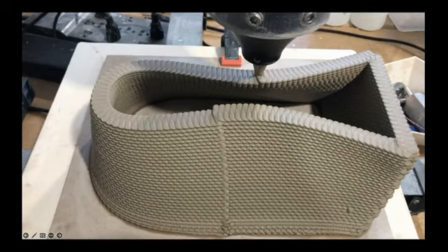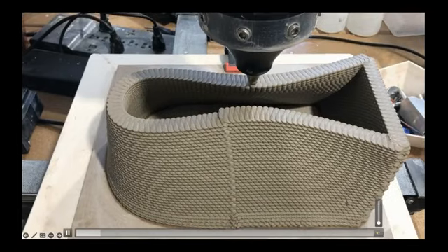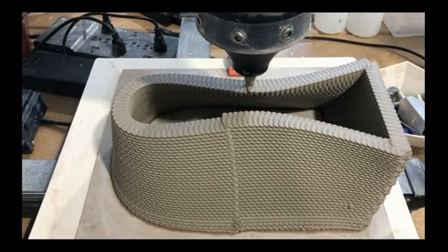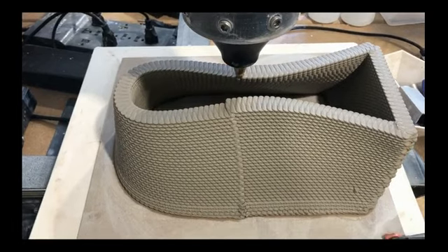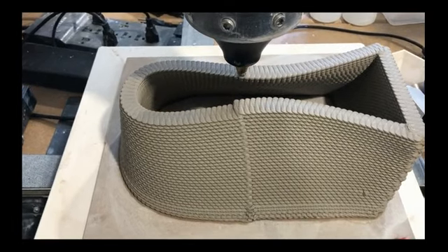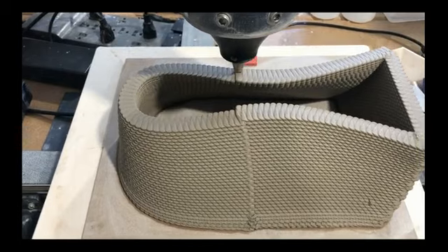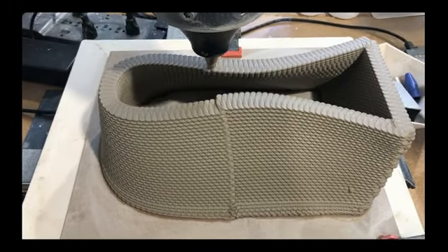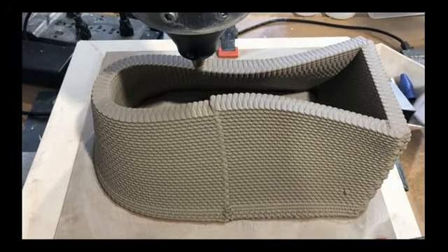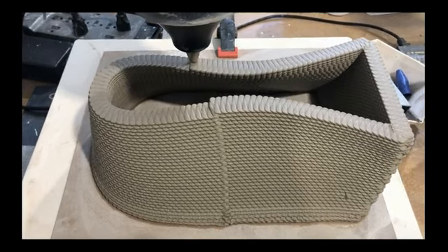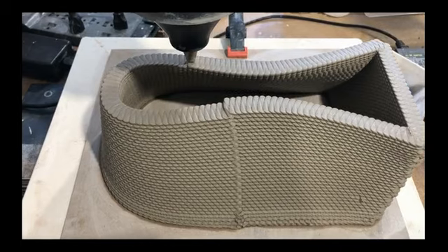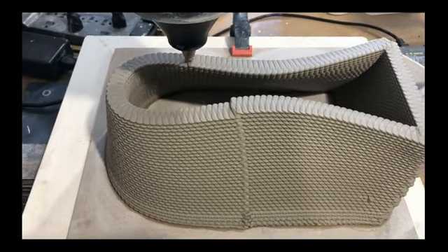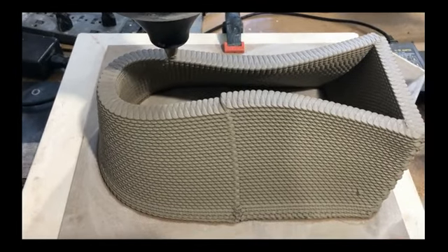This individual amplitude calculation allows for the layer thickness to vary within a form and even within each layer. So the width of the layer will increase when the form has a more dramatic overhang, as can be seen in the middle of this video, and decrease when the wall is closer to vertical, like on the right and left sides. So while it looks like the form might be thicker in the middle, if you took a cross-section of that form, it actually has uniform thickness.